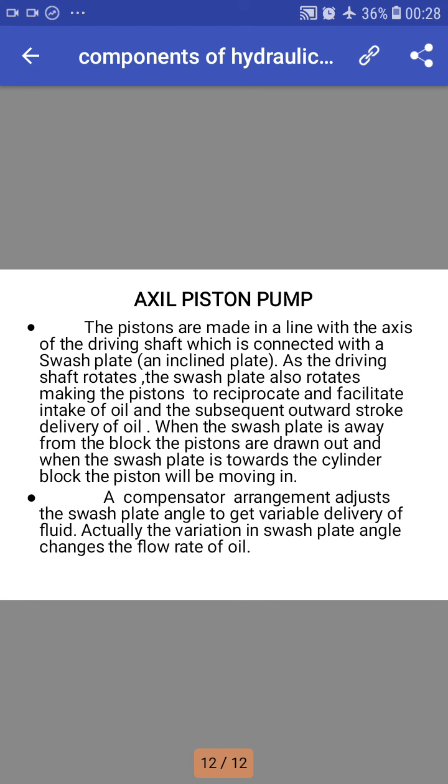The axial piston pump. The pistons are arranged in line with the axis of the driving shaft, which is connected with a swash plate. A swash plate is nothing but an inclined plate. The inclination can be changed. The angular placement of the swash plate ensures fluid in or fluid out. As the driving shaft rotates, the swash plate also rotates, making the pistons reciprocate and facilitate the intake of oil and the subsequent outward stroke delivery of the oil.